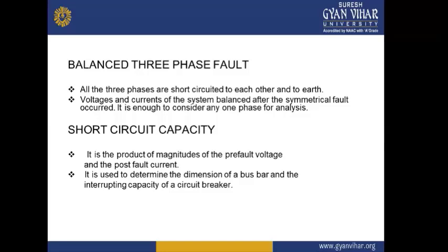When all the phases simultaneously change their fault current and voltage levels, such a fault is called a balanced three-phase fault. That means the voltages and currents of the system remain balanced after the symmetrical fault occurs. So it is enough to consider any one phase for the analysis.